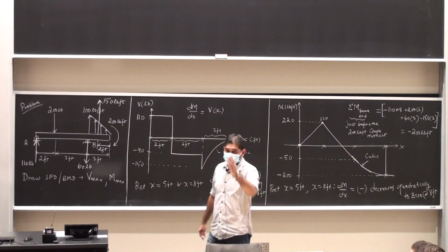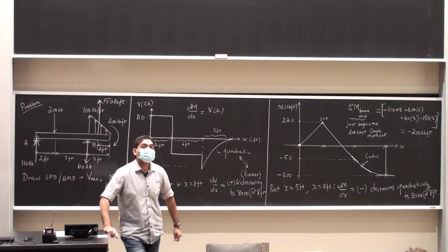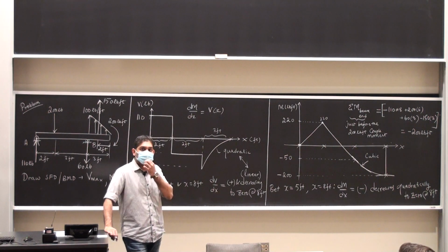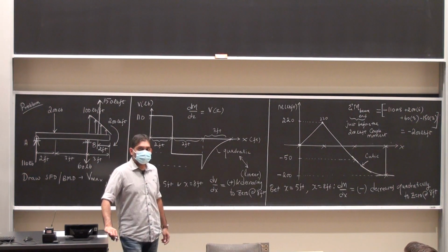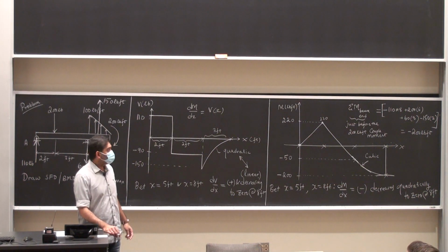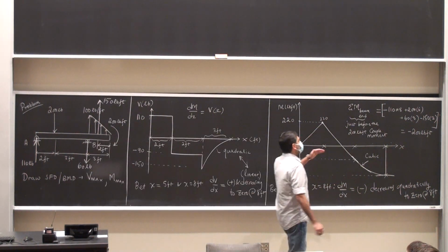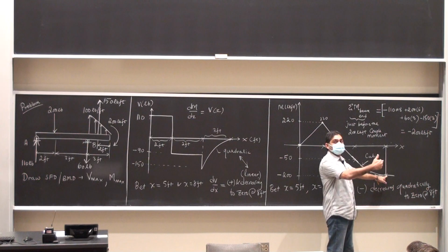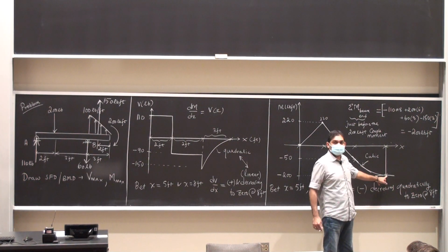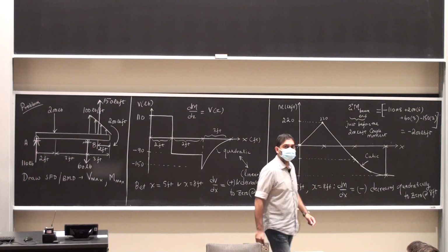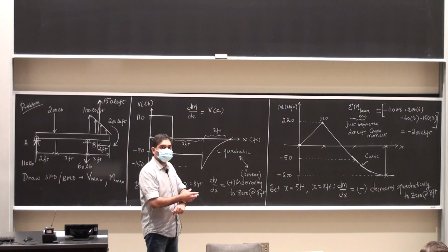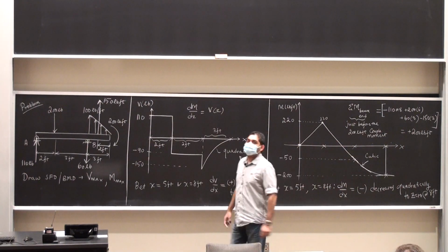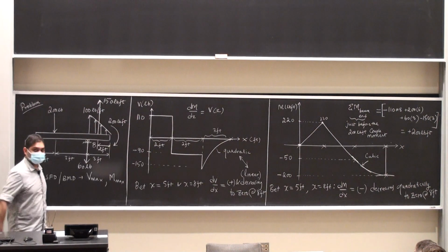Any questions? Yes, sir. So when you take this sum of the moment, I got it. So it's 200 pounds. So is it because we're assuming that that moment is clockwise? So it's like we're switching it, making that one negative, that one the positive, and then making them equal. No. So what I'm saying is, in the bending moment diagram, the value of the bending moment at that particular point, right before I hit the end of the beam, is minus 200 pound-feet. No, I know, but when you calculated the sum of the moments, it should be positive 200 if you do the clockwise, counterclockwise is positive. Right. This will end up being positive. Yeah, I'm sorry. So we're just assuming that it's the opposite of it. Right. Absolutely. That's right.